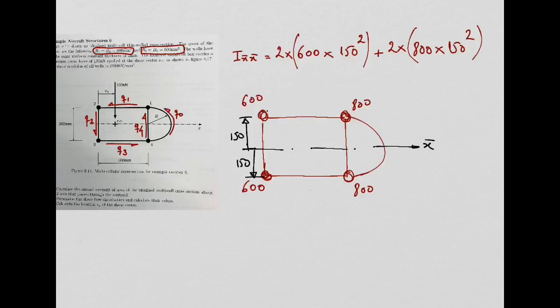Are we going to be tested on the idealized structure, or on the more realistic one, in the exam? Well, we did the more realistic one, what I usually call the full effective or the original cross-section. We did some analysis. What I can ask you in the exam, for example, is I give you a simple rectangular hollow cross-section and say, build the idealization. And then I ask you to calculate the transverse shear stresses on the realistic cross-section and on the idealized one, and compare the two. I can ask something like that.